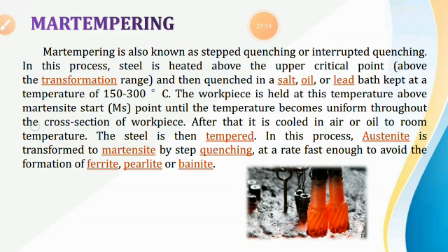The most widely used austenitic steels contain 18% chromium and 8% nickel. Such steels are commonly known as 18 by 8 steels. These steels are non-magnetic and possess the greatest resistance to corrosion and good mechanical properties at elevated temperature.